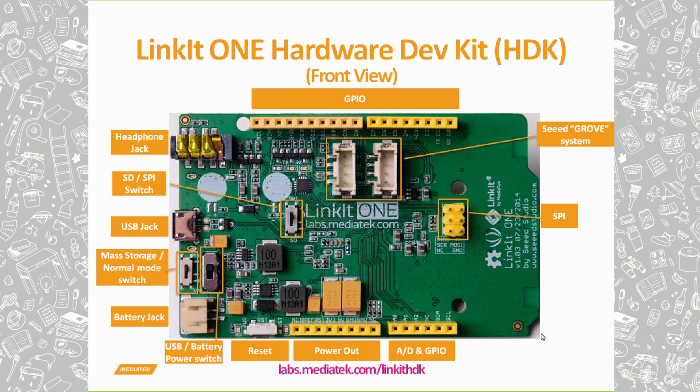You can switch it to mass storage mode and switch it back to UART mode if you want to just upload your sketch. It's also important to check this switch position when you update the firmware, because it has to be in mass storage mode. And then the switch right next to it is to choose your power source. You could either choose USB or the battery.